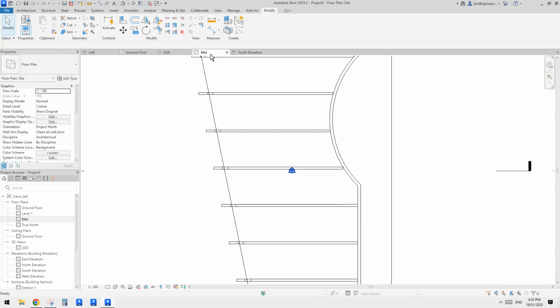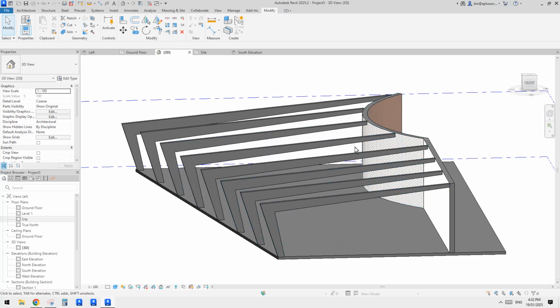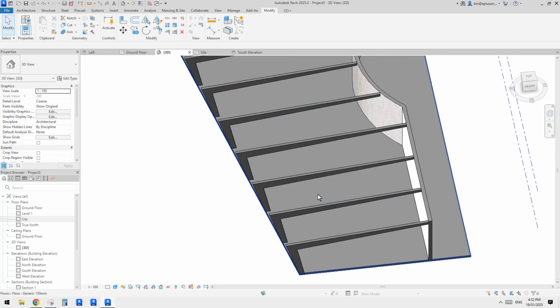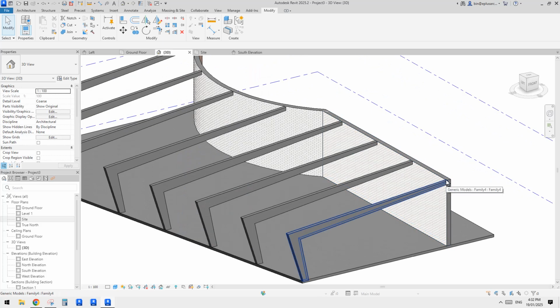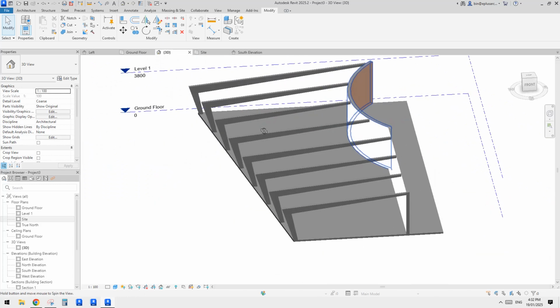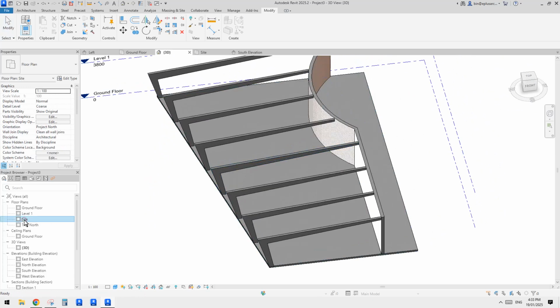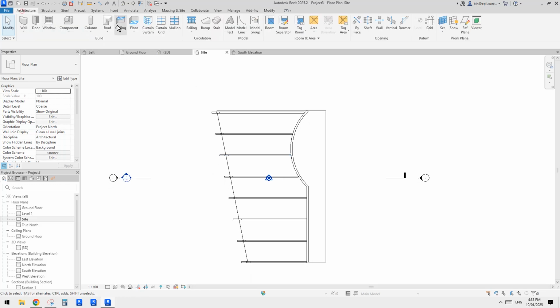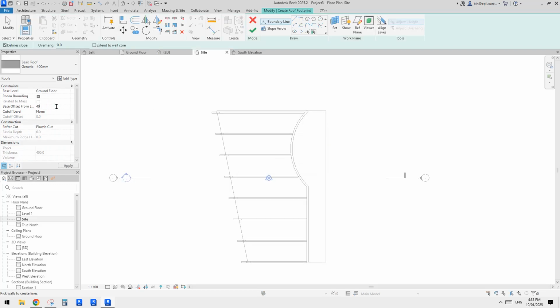But the issue we will have here is when we create a roof with this slope direction, all the height here will be different. So for example, this one here will be higher, and at this point will be lower. Yeah, probably the same, but it will be different height. So let me show you why. Okay, so let's do a roof. So I'll just maybe just current for now. I'll just use ground floor with offset maybe 4 meter, maybe 3 meter for example. Okay, so 3 meter, and I'll just use maybe pick.